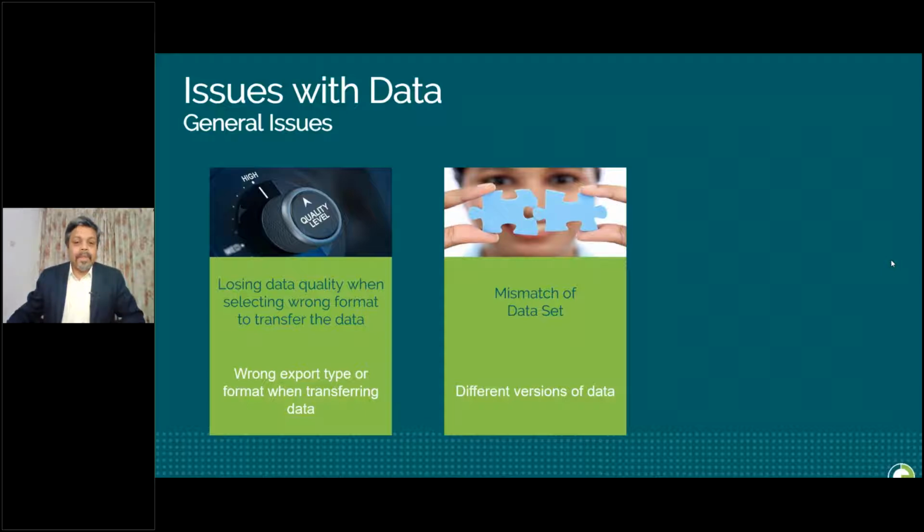For example, if you have a Tekla model and the client is generating MTO from the Tekla model and providing it for the work packaging scope, this can be avoided as we provide an option to generate MTO from the 3D model. As soon as a new revision of the 3D model is available, MTO will be generated and updated in the project. This is just an example.